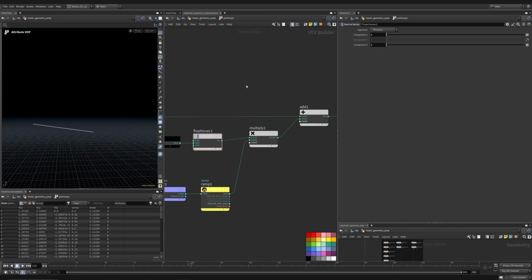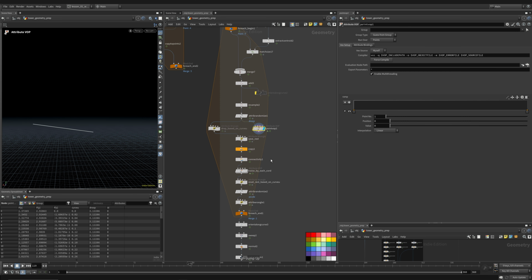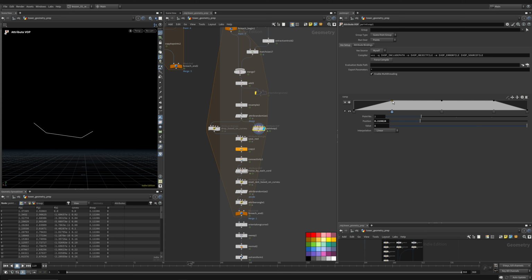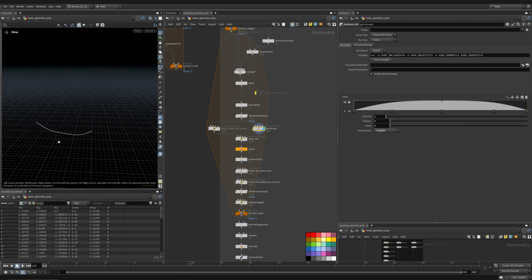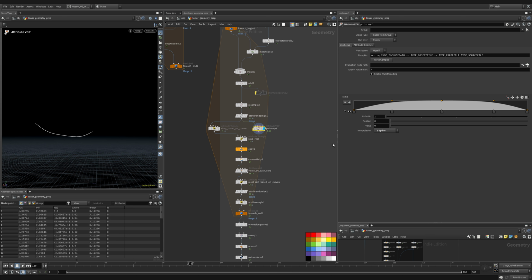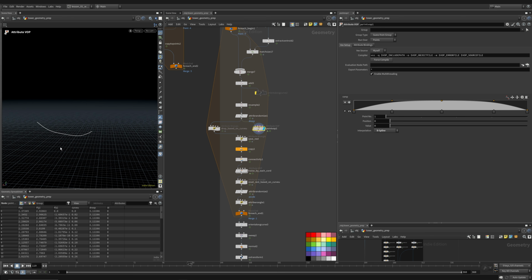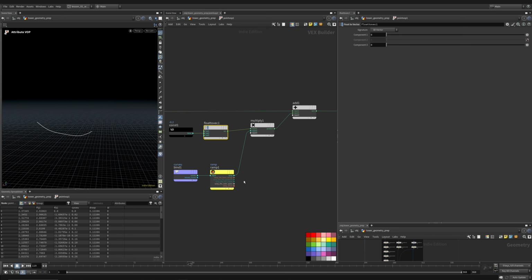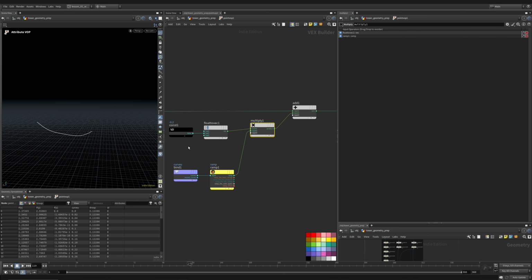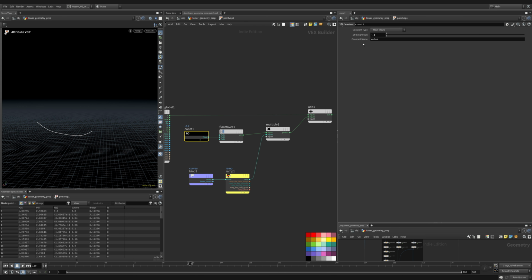And now that'll put it back to 0. But if we go up and select this ramp to adjust it, we can now control where on this curve our object is being displaced. I'm going to set B-spline. Now if we wanted to make this smaller or taller or higher, what we would do is middle mouse button and promote this parameter.